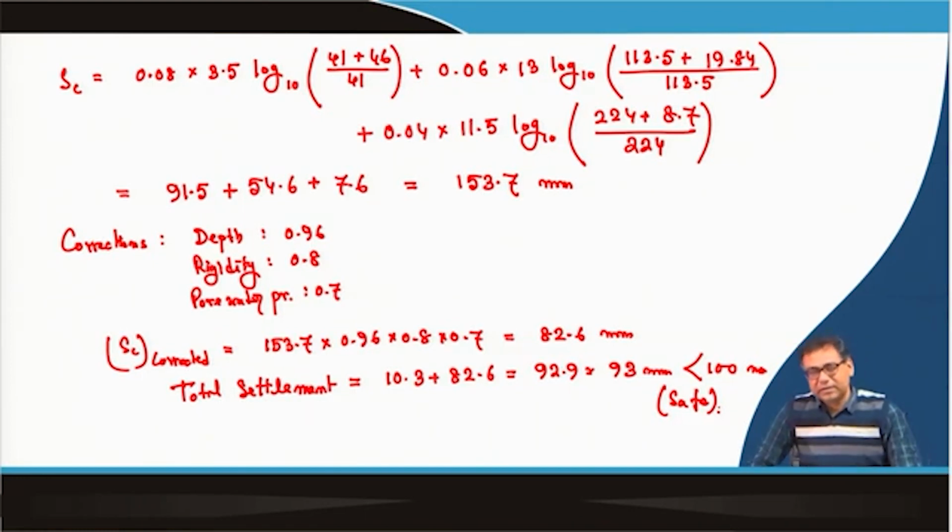So, I have finished the shallow foundation part. In the first module I discussed how to determine the soil properties by using different field tests. Then I discussed the bearing capacity calculation, then the settlement calculation for shallow foundation, then I gave you the concept of beams on elastic foundation, and how you can establish the interaction between the foundation and the soil, and then determine the bearing capacity, bending moment, shear force, and settlement of the foundation.